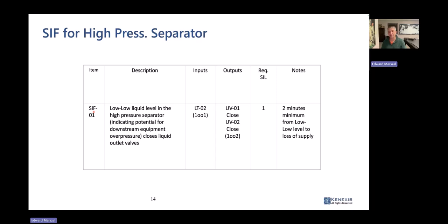I was trying to make things easy for the participants, but if you are an aficionado of the ISA 5.1 standard, you know that the SIF would be safety indicating, and I don't even know if there is an F as the last item. This doesn't meet the requirements of the ISA standard for how you define safety instrumented functions.